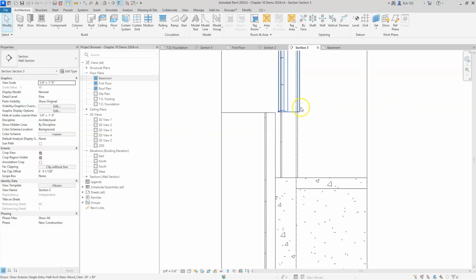Now, where we placed level 1 when we first created this project was determined, and we're going to have another separate conversation about this in the future. But if you're wondering how we know how high to place that level above the foundation, the answer is we have to engineer the floor first. Part of engineering the floor is figuring out how big the joists or trusses are going to be, and then accommodating that by raising the top of that floor up to accommodate the floor, the subfloor, the floor structure, and then anything else that has to happen underneath that, like the mud sill.